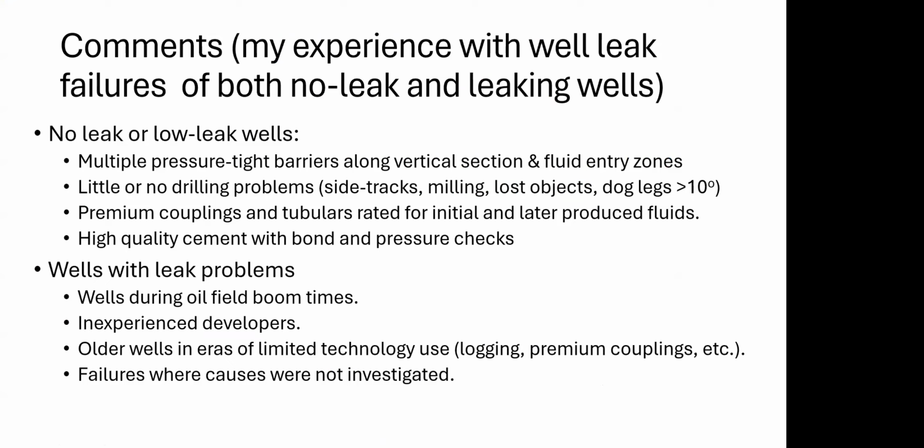So the comments, and this is my experience, no leak or low leak wells have good pressure type barriers, little or no drilling problems. You start having drilling problems, sidetracks, those types of things, and I'll cover that in a moment or two, you're going to have problems. One of the problems that is still with us today is we're using the non-premium connections in the casing, and those are not gas tight, and their seal will last only as long as the thread compounds will. So this is one thing we've been trying to get companies to move away from, these 8 round or other types of threads that don't have good steel to steel sealing. All right. But the bottom issue here is you've got to have high quality cement over this whole zone. Oftentimes, cement is an afterthought, and it really should be the most important thing coming. Because if you have good cement, that well is going to last for a long, long time.